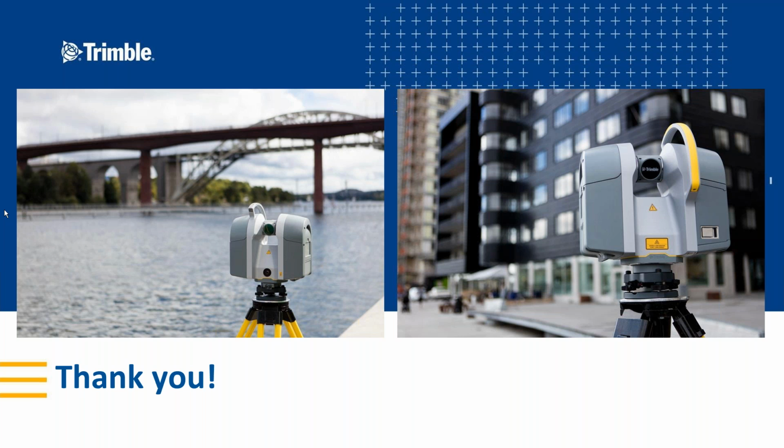What scan modes would you use to scan road surfaces for inspection purposes? With the TX8, you could use the extended range mode in order to capture larger areas at a single scan, but I would recommend the level 2 scan mode.